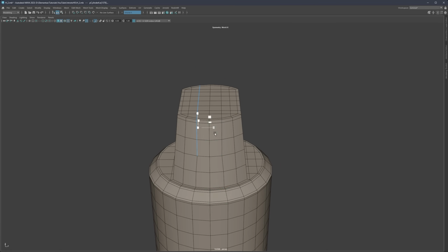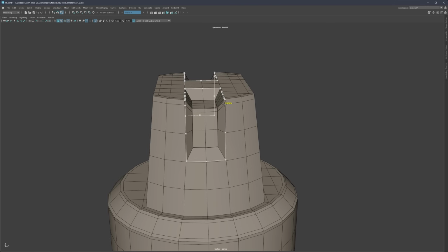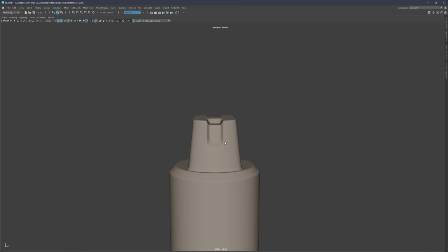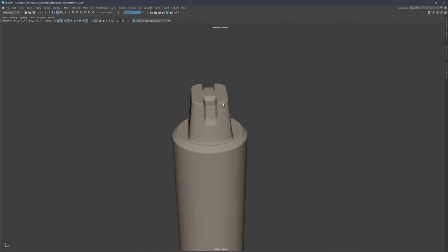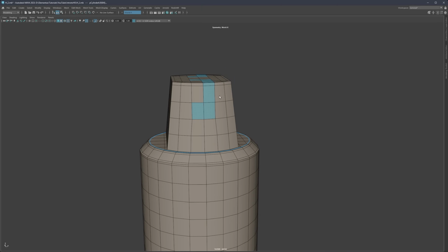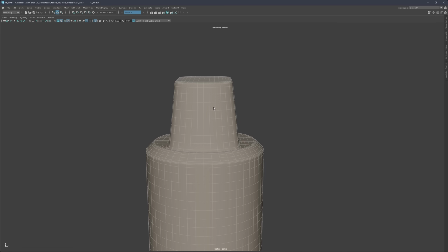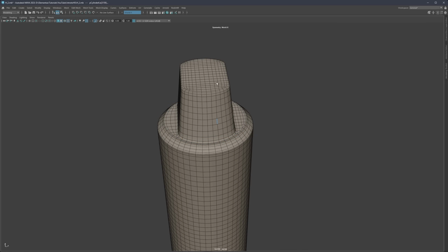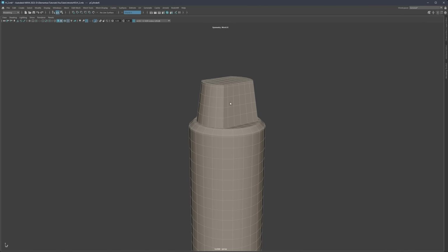And now, if we select these two parts and create a detail, we're going to have more of a straight line here. It's no longer going to be that much of a crazy curvature. So that also means if we do it here, and later when we subdivide, so add more smoothness or subdivision, that curvature will be maintained, and maybe slightly we're going to need to adjust that. And there we go. So now we are also prepared for that.